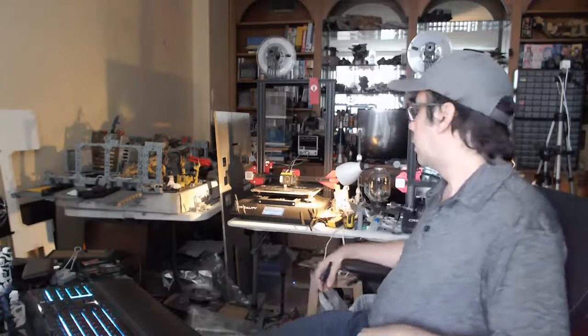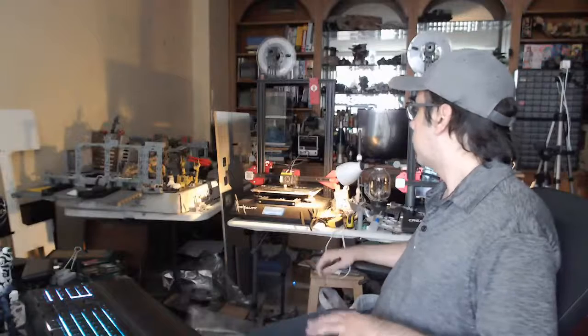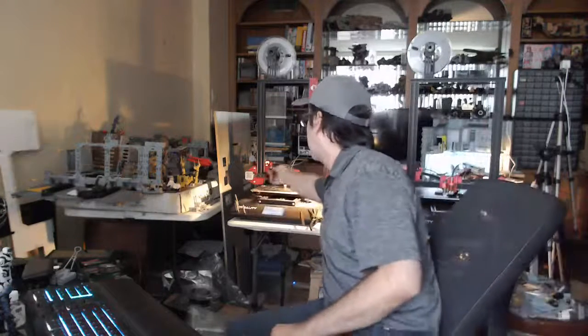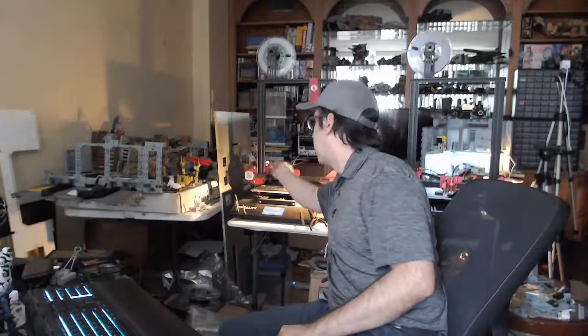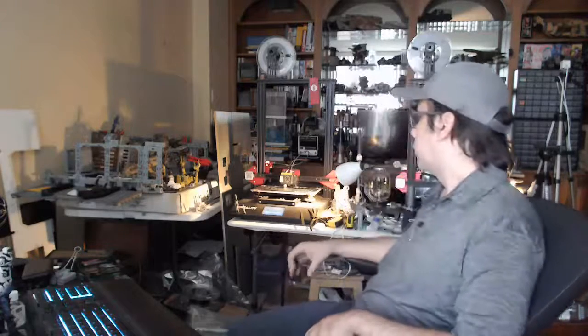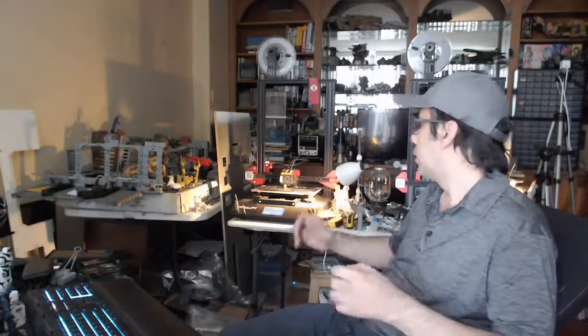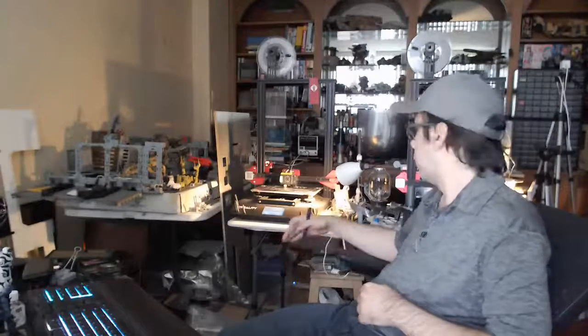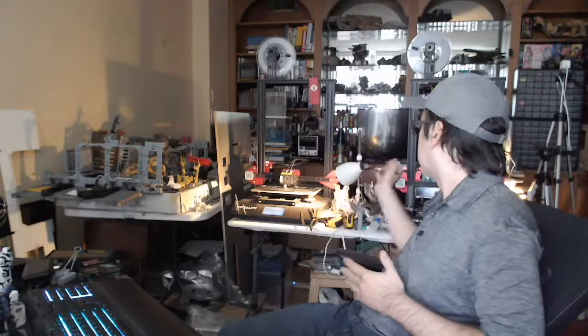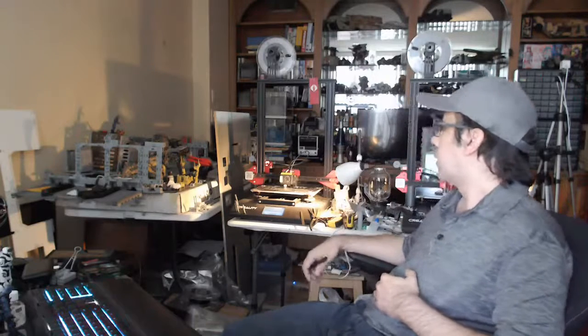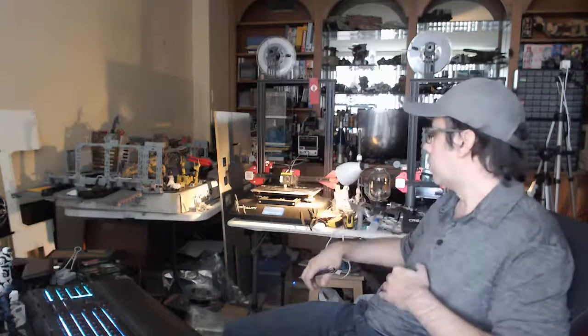Now, these printers are very good, but they require a lot of hands-on work. Part of the issue is that they have a lot of weight on top of the bar here. When the machine is off, there's no tension on the stepper motors, so any vibration or jarring of the table sometimes makes the weight begin to work down on the stepper motor.